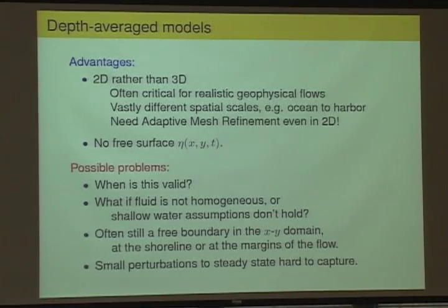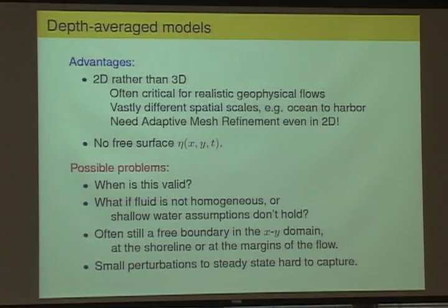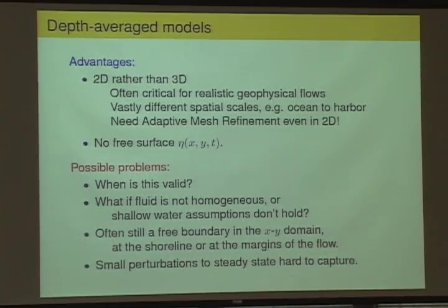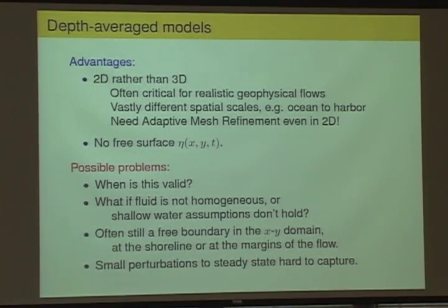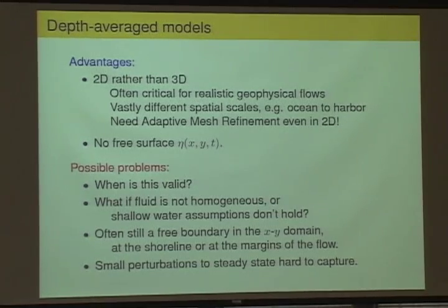But that does give problems in implementing these methods. If you look at the partial differential equations that model the shallow water equations, say, or these other depth-averaged models, if you have a cell that's dry adjacent to a cell that's wet, then you've got an interface where you've got depth 0 on one side, non-zero on the other. You have to do something special to look at how the water spreads into a dry cell from a wet cell. You have to worry about cells drying out without the depth going negative. If the depth goes negative, typically things go wrong, especially since the wave speeds that we need to calculate go like the square root of gH for the shallow water equations. So if H is negative, you know it right away. So you have to put in various things to make sure that the algorithms remain robust.